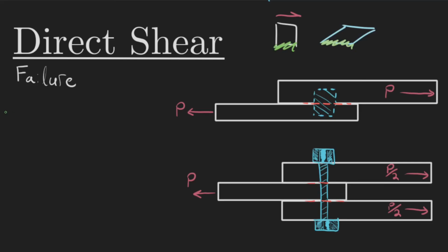So the shear stress, again, is just equal to the force over area. So force over area, except now our area is parallel to our force. So if we go ahead and look at this beam right here, for example, we would have our P divided by the area of whatever this little cross-section of this blue thing happens to be. But in the case of this double shear joint, what we would have is, let's say that you look at this little beam in the center right here, right? I have this load P, and the area that the shearing is distributed across is this area right here, and also this area right here. So for this part, I would have our shear stress, which is the letter tau, equals P over 2A.